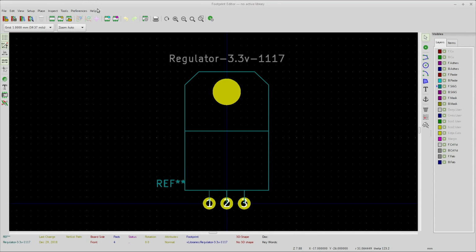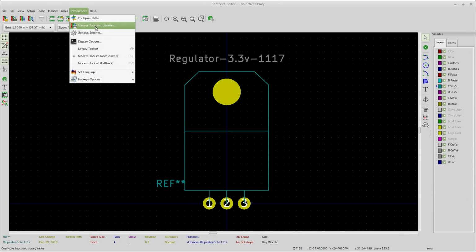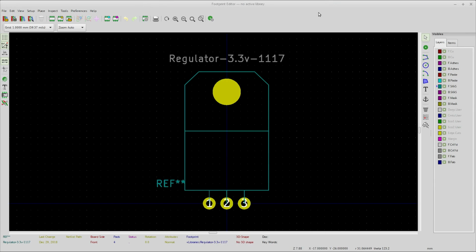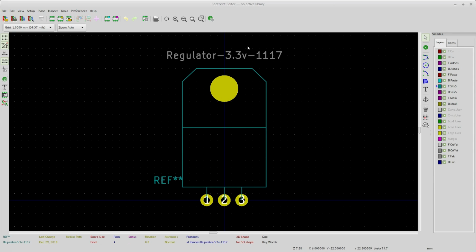And in this case, though, we learned about going up to manage footprint libraries, and we stored these footprints inside the same computer library that we had our other ones, so that everything would be in one location. We also talked about separating them. Once we got to here, we started consulting the datasheet for the mechanical properties of this, as in where are the holes placed. How do we place them?